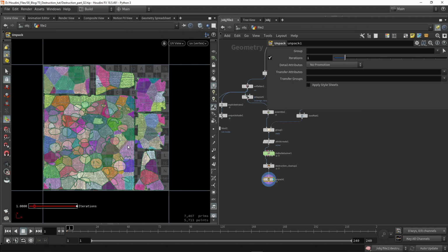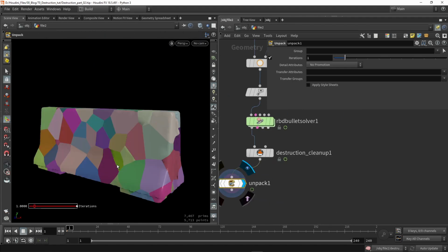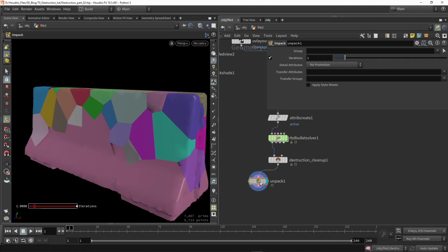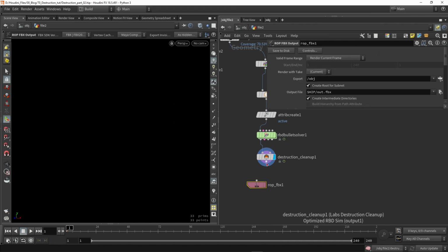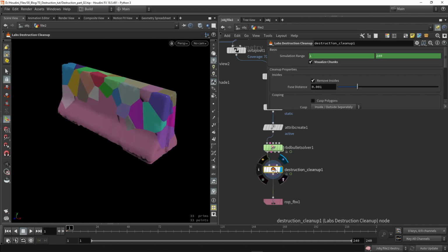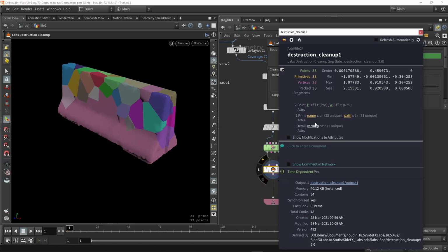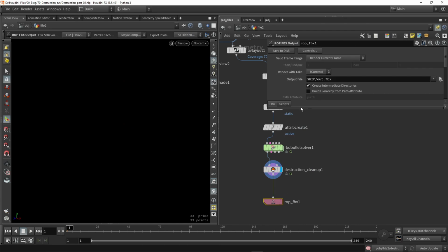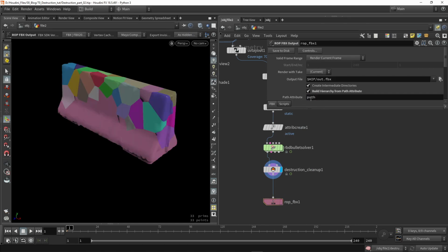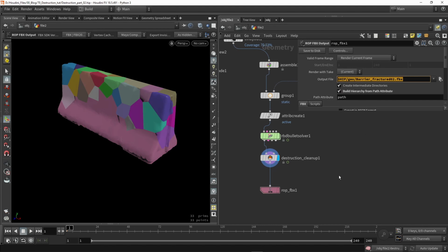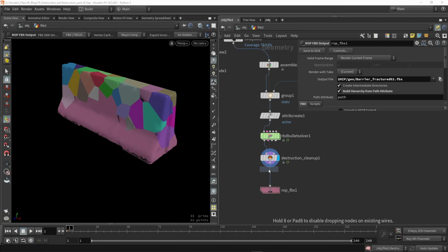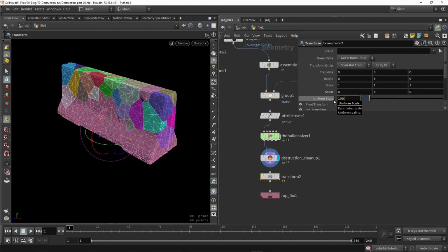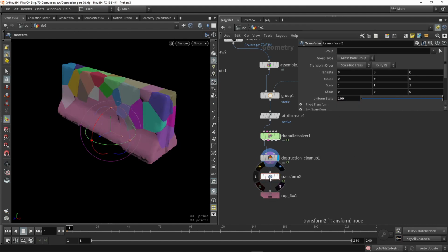So that's basically it, and we're almost done with the Houdini part. So let's think about using an FBX node. And again, from the last video, we need to use the attribute to define the exporting. So we're going to use here path. So let's do path here because the pieces are done separated. Let's give this also a proper location to save. And also let's scale up our model back to 100 units. So that's also important to do. So then we can click save.